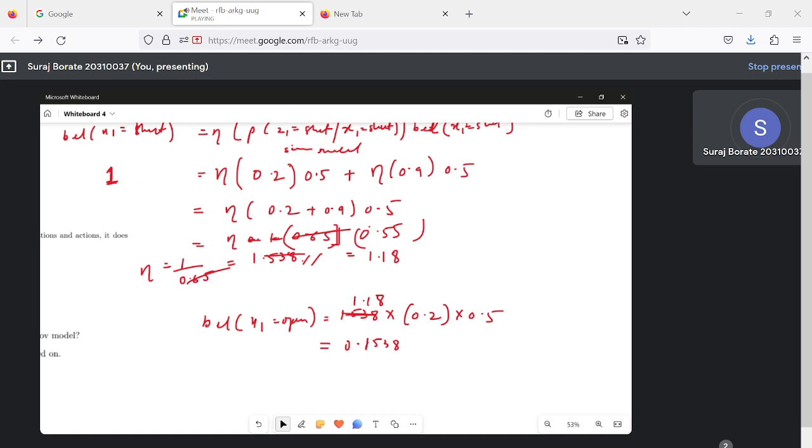And in the next question, when we are solving for belief at x2, all that we needed was belief at x1, right? And the action at u1 and the measurement at x2. So we don't require x0 for x2, right? We only required x1. So the entire history is not required,